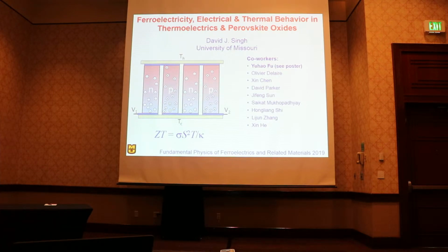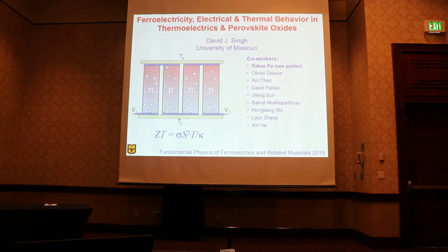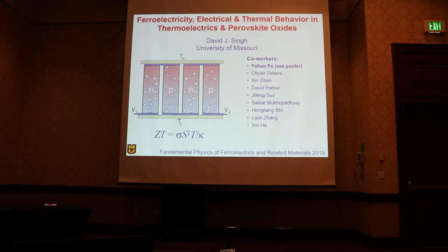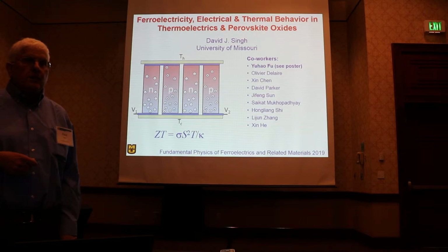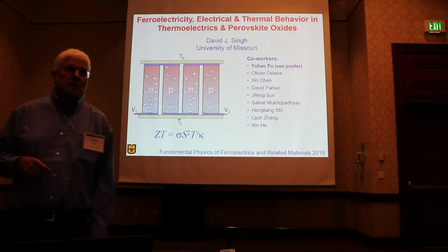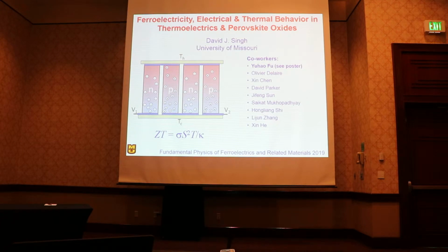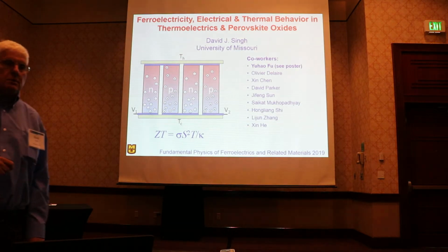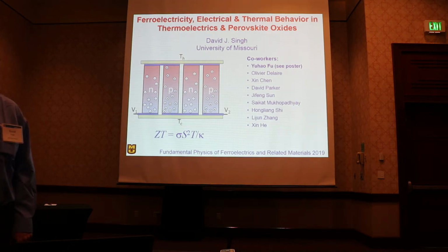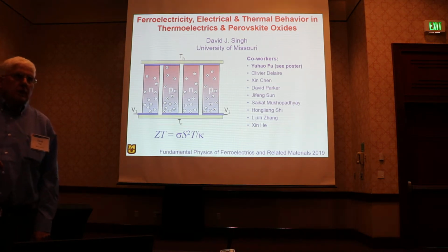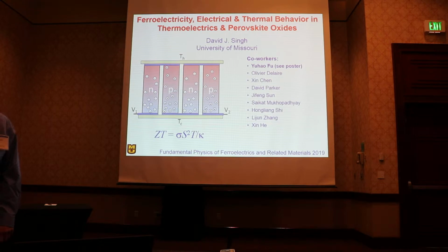So what's different? Well, charge carriers in semiconductors are fermions, so when we do our Boltzmann transport theory, we should use Fermi-Dirac statistics instead of Boltzmann statistics. And also, they don't follow the parabolic dispersion of classical particles, p squared over 2m, but they follow the dispersion of the actual band structure, which we should consider.